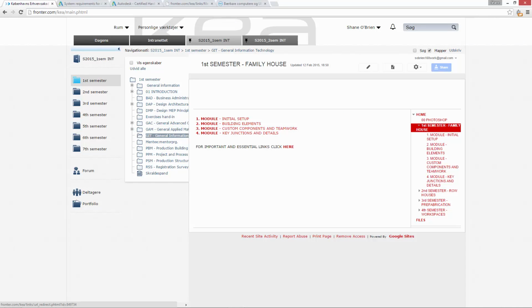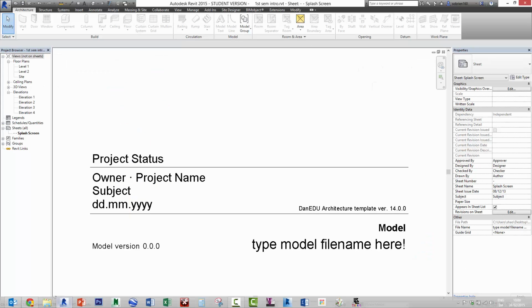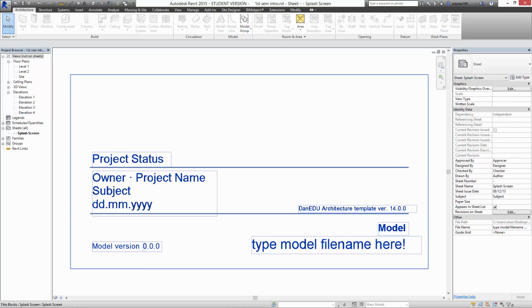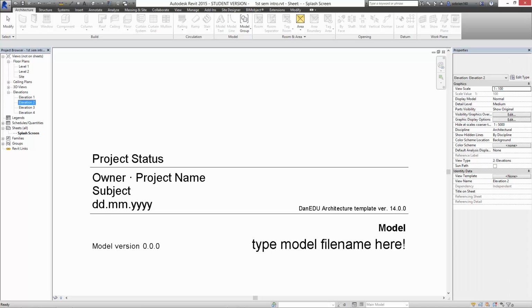Okay, guys, I'm going to do some Revit. I'm going to take the little house we were building forward a little bit more. I realized that the template I've been using is actually the previous one to the ones you guys have been downloading. They've made an updated one since I downloaded this last month. So the reason you're not getting, for example, over here on the left, 4 elevations, you're only getting 1 elevation, is because you've got a more updated template than I had when I started the project. So it's not wrong, it's just nobody told me, so not my fault.